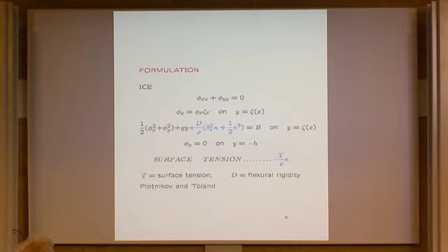We have a potential function phi satisfying the Laplace equation. We of course have here the classical kinematic boundary condition. There's no time appearing, since I'm now in a frame of reference moving with the wave. The usual dynamic boundary condition. And if we have a bottom, the kinematic boundary condition on the bottom.